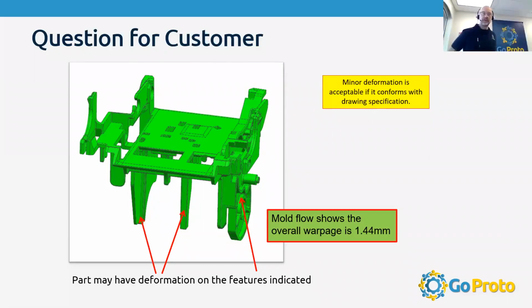Yes, absolutely, it can. Zero draft just means that there's no draft, no angles at all. So when the tool's ejected, I mentioned in the slide before that it can create some scuff marks. It also can sometimes, let's say you have a circle, a hole feature, with zero draft, and it shrinks around the core pin that makes it. When you pull it, it can actually cause that hole to pucker or change shape as it pulls out. It can create kind of a crater. It can definitely affect the tolerance on certain features. That's just one example. The short answer is yes, it can affect dimensions.